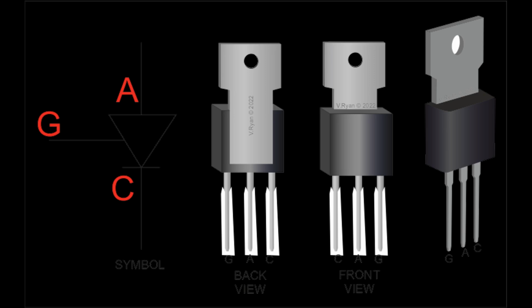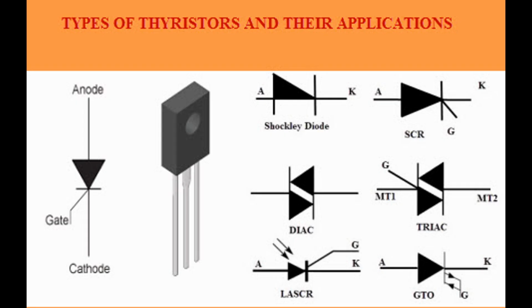Advantages. High power capability. Suitable for applications requiring the handling of large amounts of power. Fast switching. Provides faster switching than traditional thyristors, improving efficiency and performance. Integrated gate drive. Simplifies circuit design and improves reliability by integrating the gate drive circuit. Low inductance. The low inductance design of the gate drive circuit reduces switching losses and improves performance.